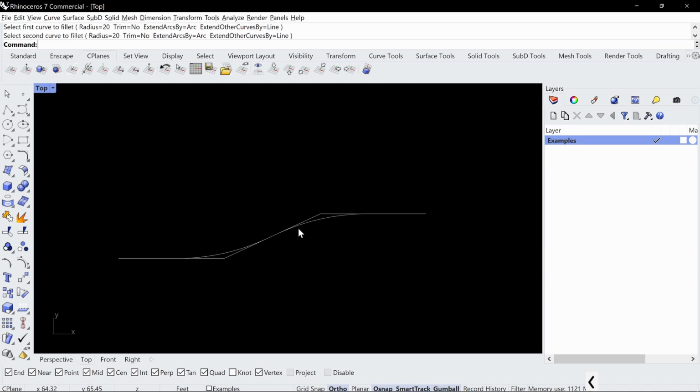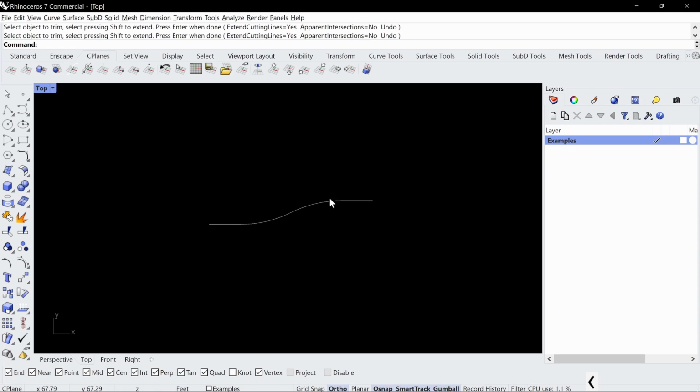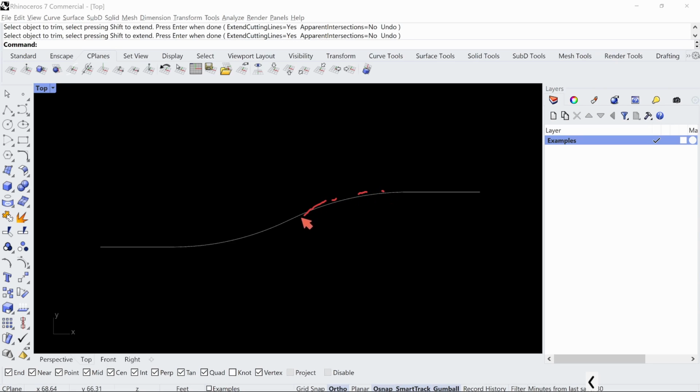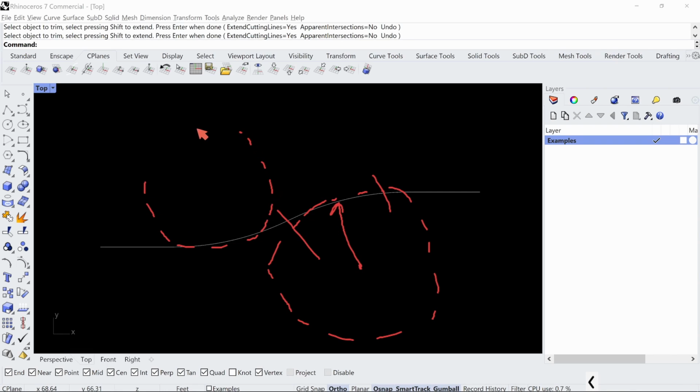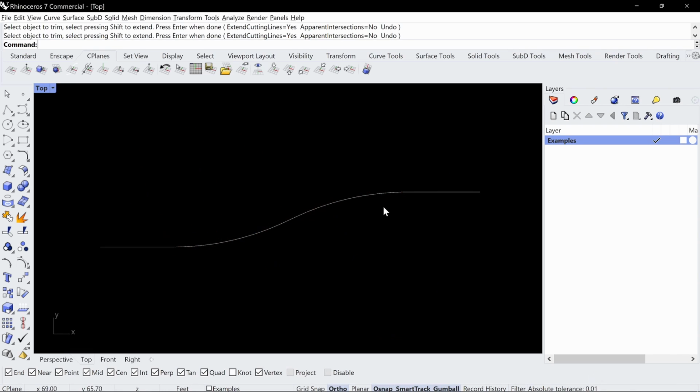So this is like an exact geometry. Maybe in a professional setting, you might want to do something like this because now you're working in a very exact geometry. And if you're doing construction documents, you could literally call out this radius. You can call out the radius and the arc length, and show them that this is a true perfect radius of 20 feet. The same thing here. This is pretty helpful. But again, at the schematic level, you don't have to worry about that level of specificity. Just worry about the form finding. I just want to show this to you, help you understand all the options of creating the same thing in Rhino. So that's another option.